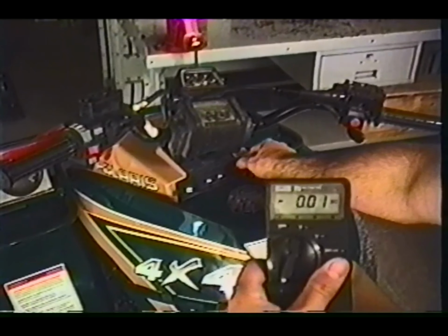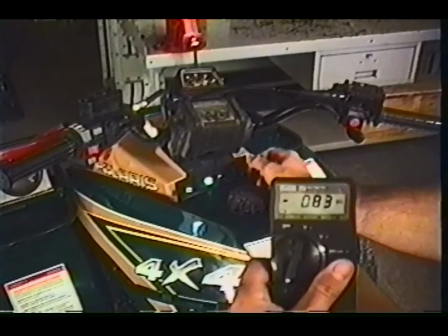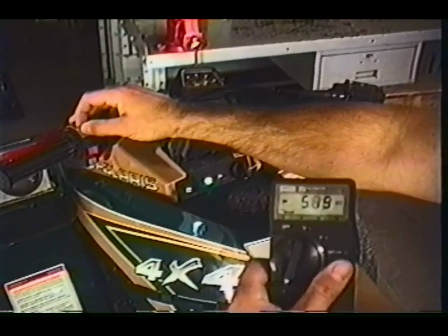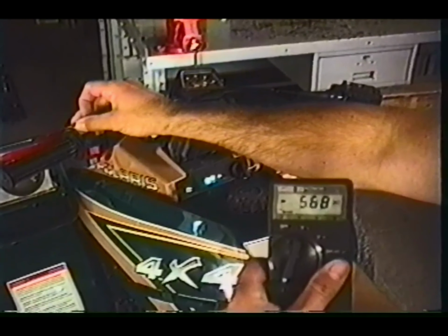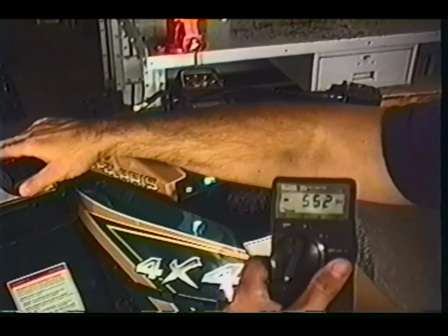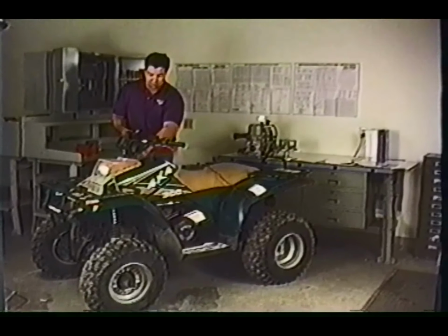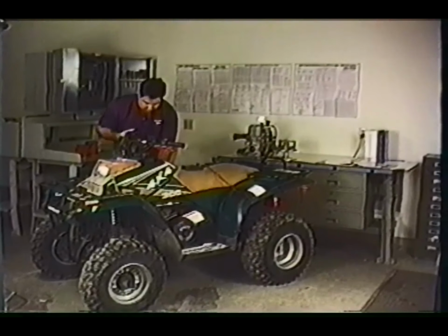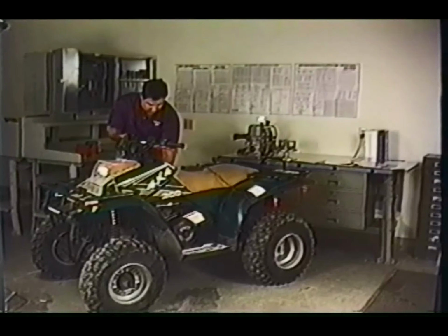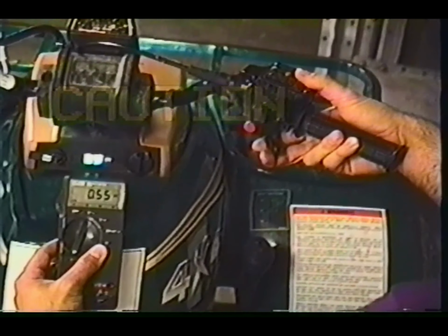Another way to test an alternator is a break-even test. With the amp meter in series as described above, the meter leads fastened to the battery and ground cable, you should turn on all accessories and observe the current draw created by each one. Start the engine with the recoil only. Do not use the electric starter to start the engine. This will put excessive load on the meter. Never connect or disconnect the amp meter with the engine running. Damage may result to system components such as lights and the rev limiter. Once the engine is running, the Fluke amp meter will show a positive sign if the battery is being charged by the alternator.